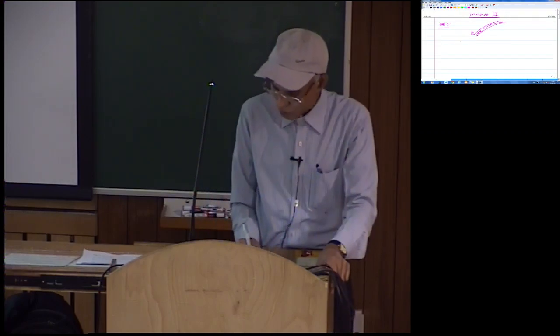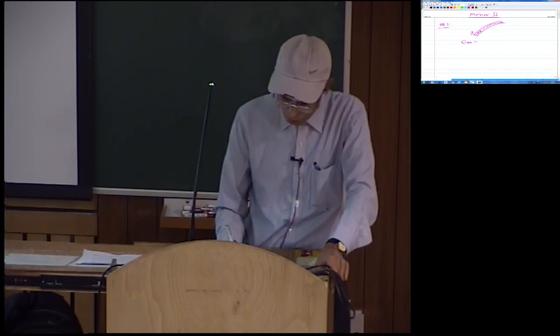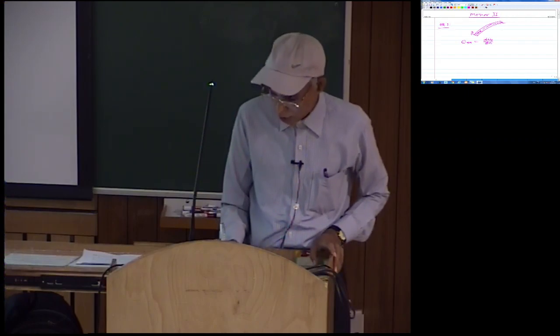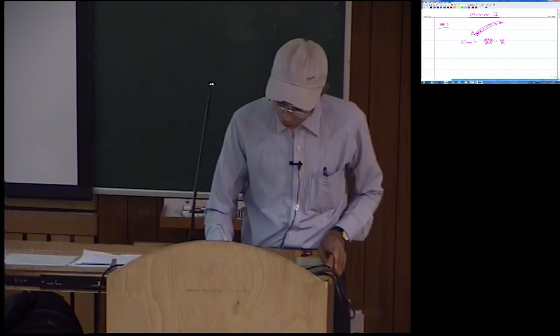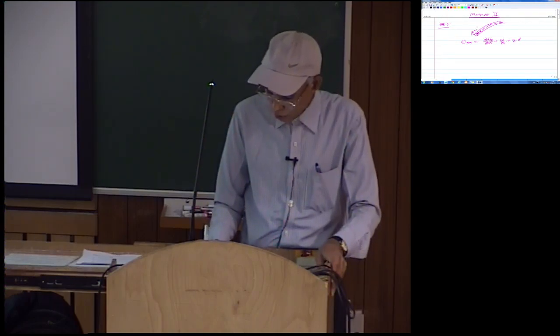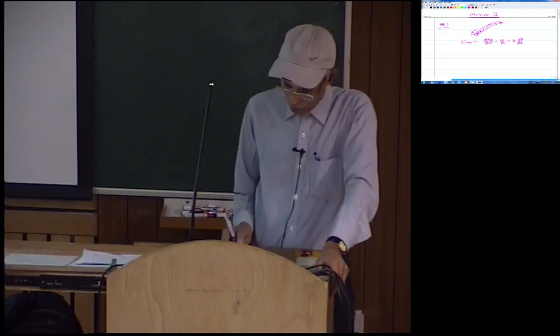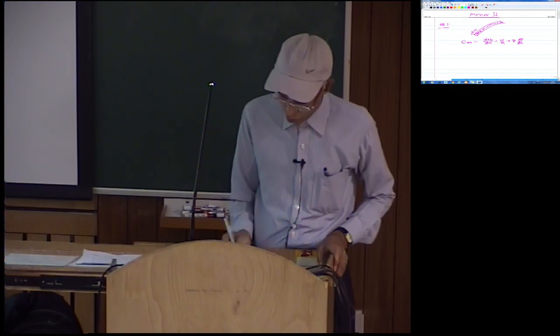For this it was given that the normal strain epsilon xx along the x direction at any point having coordinate z is given by du naught by dx plus w by r, plus z into d theta by dx. Here u naught is the displacement of the point on the centroidal axis along the x direction, w is the displacement in the normal direction, and theta is the rotation about the negative y axis as per this coordinate system.